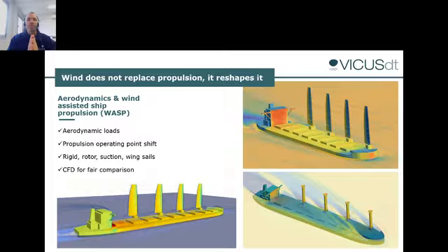And we need to make sure that the impact on the propeller and the rudder is not making the gains vanish, because by the fact of having my sails operating, I need to make more frequent course corrections, or I need to have the rudder turn 2 more degrees on one side. This has an impact on my propeller performance. It has an impact on the resistance of the rudder as well. And it's not something to be disregarded easily.